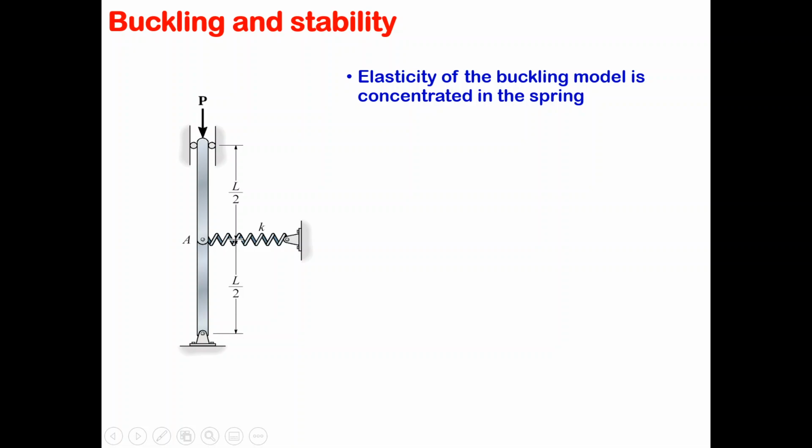You just have to keep in mind that in our modeling of the buckling phenomena, we are assuming that the elasticity of the buckling model is concentrated in the spring. The real model can bend throughout its length. That's very important. But in this model, the deflection is going to be concentrated in the spring.